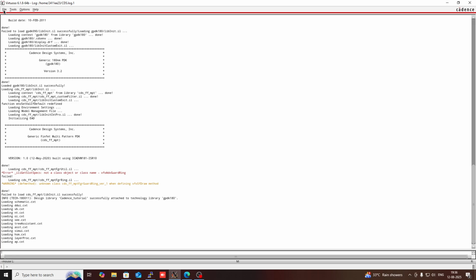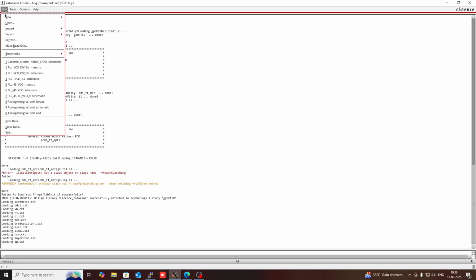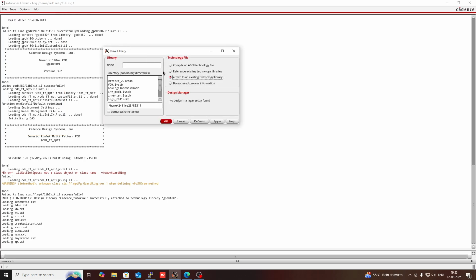First of all you have to go to File, then New, then Library, and in the library dialog you have to give the library name. I am creating a library called Cadence tutorial. So this is basically my library name, Cadence tutorial.